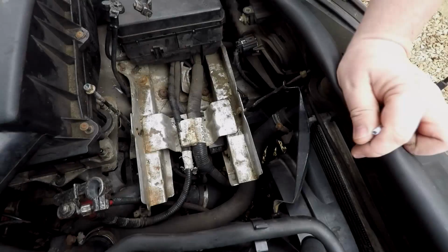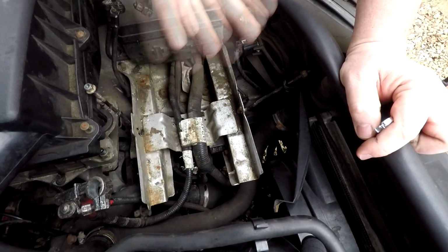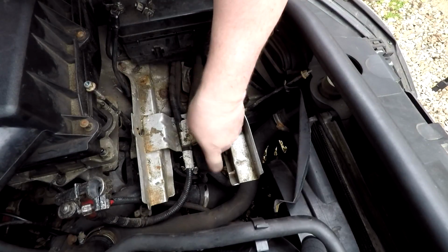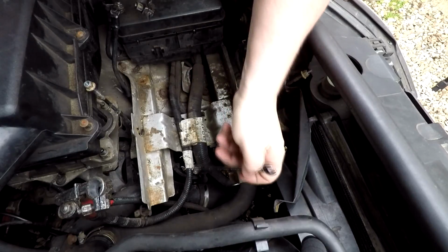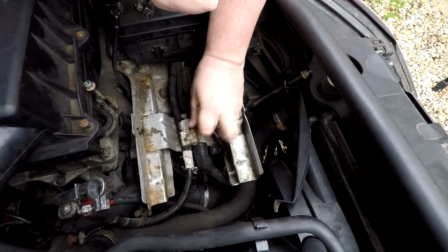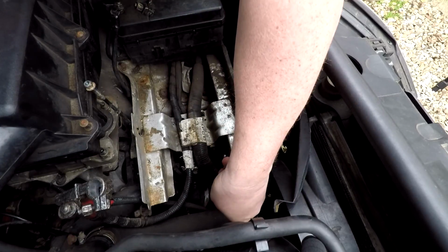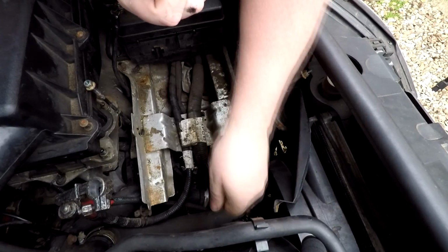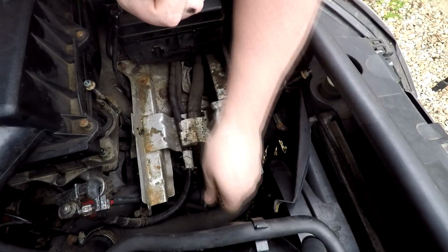Right, okay, as you can probably see here now that I've taken the battery out again, that is just to reveal where this relay is situated down here, and it's held in by an 8mm bolt. So I'm just going to undo this, and we can hopefully withdraw the relay and just take a look at it, and as I said to you, lubricate things a little bit.